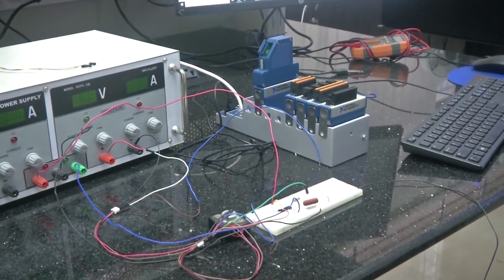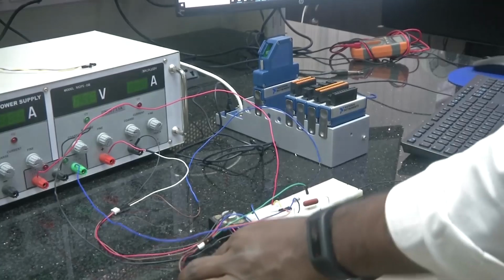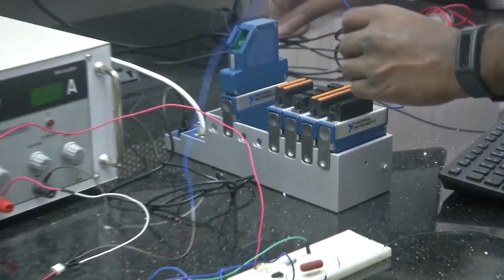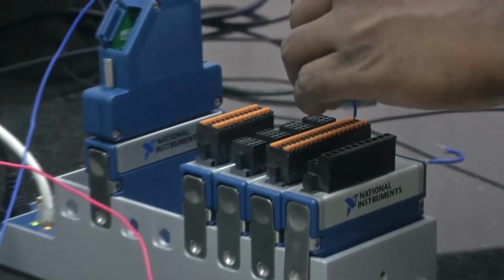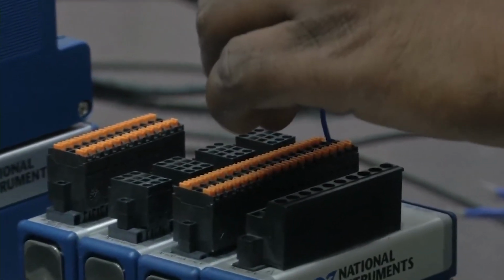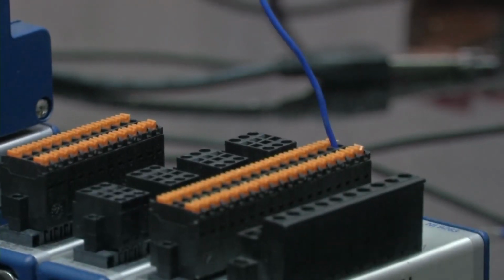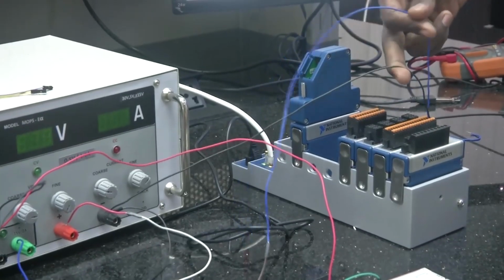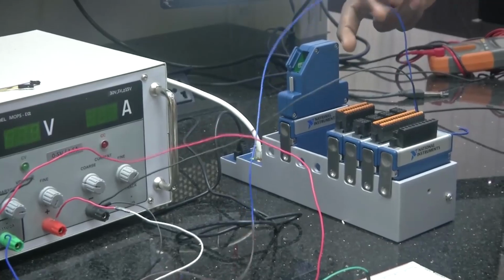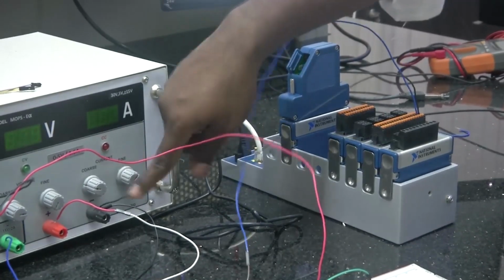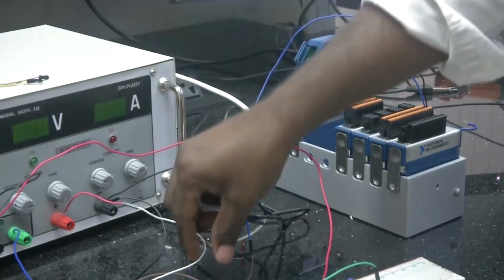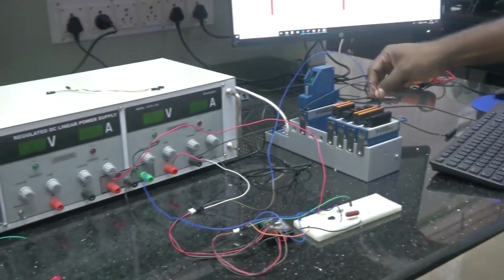So what I will be doing is connecting the temperature sensor output to the first channel. Since it is a spring connection, press connect. The output is connected, and the ground also has to be connected here. I have shorted both the channels, negative terminal to negative, and to the power supply. The output of the LM35 is connected as an input to this.